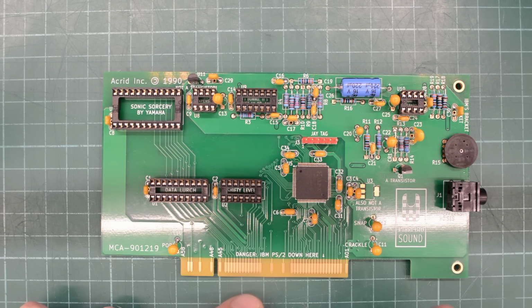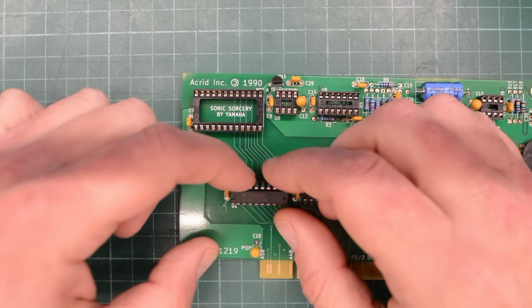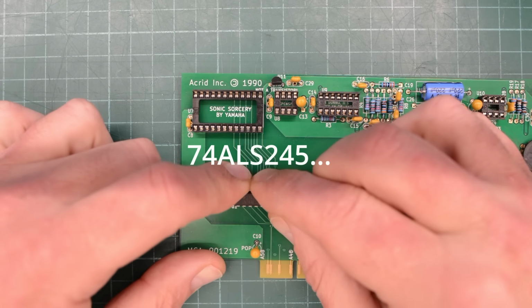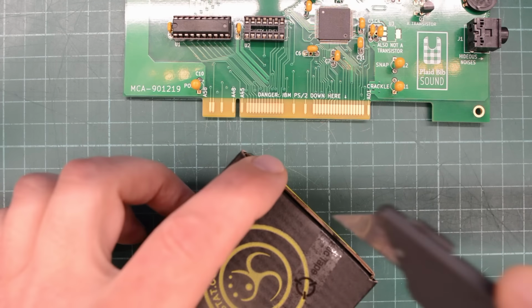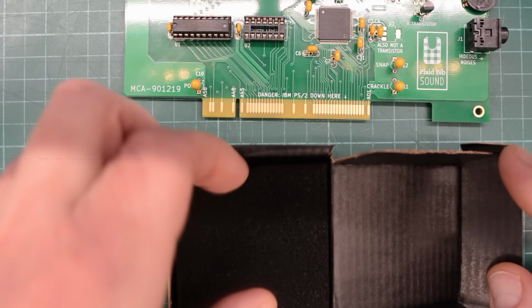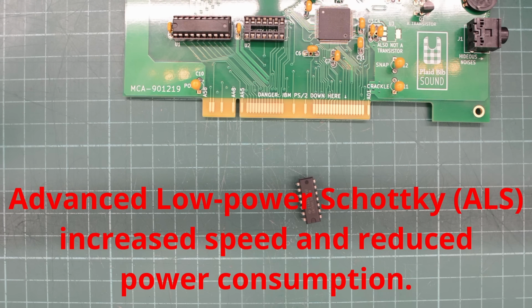This is where I normally would wash the board, but to get the video out on time I'm gonna have to wash it later. So let's get some chips in those sockets. U1 here is a 74LS245. Next up we have a 74ALS04. I'm not sure if it has to be an ALS series.